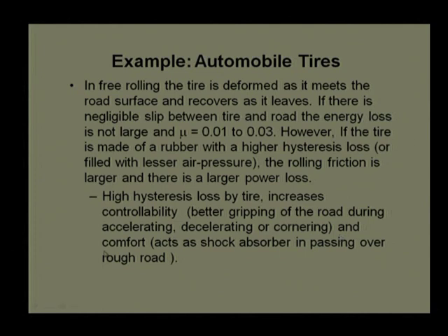In addition to that, this deformation provides some sort of comfort. It acts like a spring action, or a part of a shock absorber. It does not transmit all road unevenness to the passengers. So, from the comfort point of view, some elastic deformation needs to be there, or the rubber material needs to have that kind of deformation.